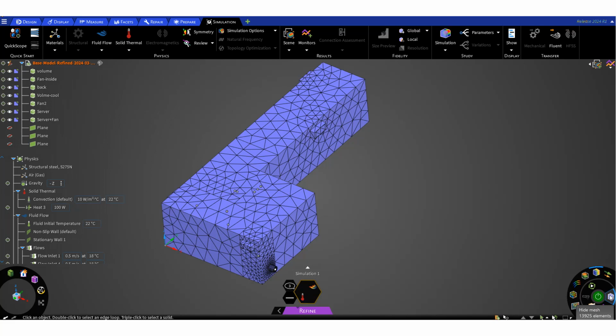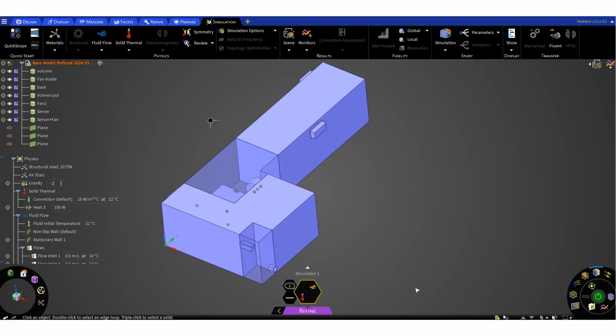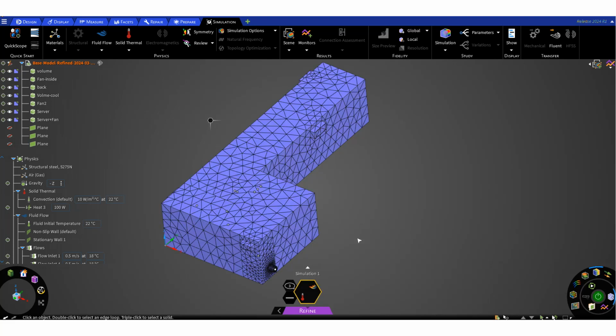As you can see, almost 14,000 elements and about 5,500 nodes. So we have the information about the nodes and elements readily given, and we haven't solved the model yet. Let's increase the fidelity to see what we can have. And the meshing started. If I check the number of the elements, from 13,000 it increased to 20,000 elements, and from 5,500 to almost 7,400 nodes. Go to the high fidelity by the slide bar,